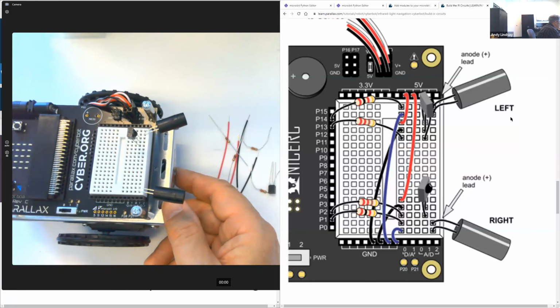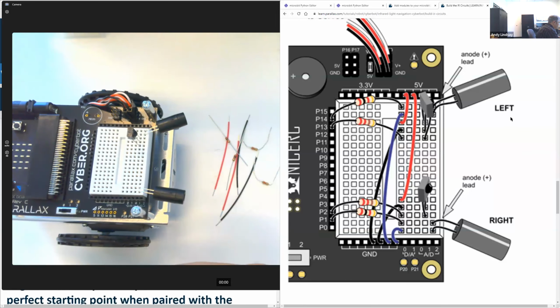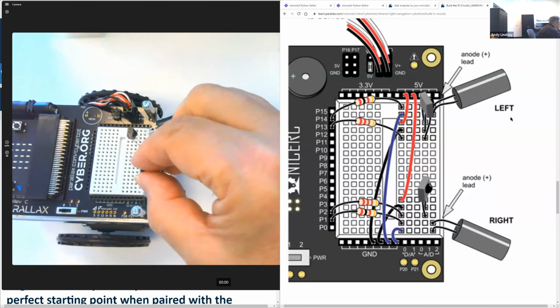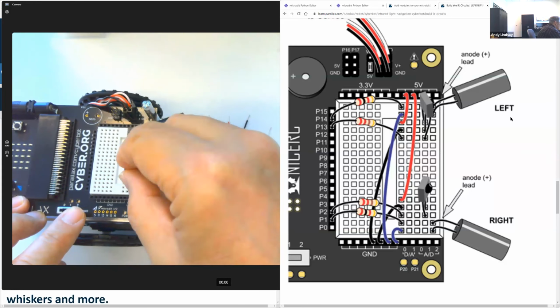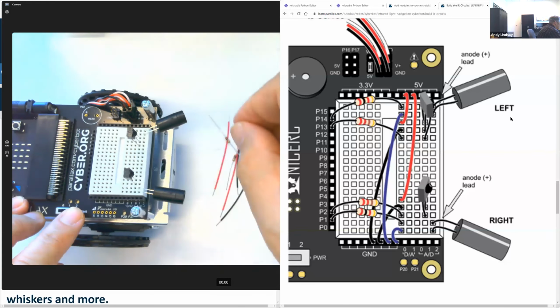When you apply voltage to the red bulbs, they have to be in a circuit with a resistor, and they will typically show about 1.6 volts. And then the resistor will show the rest of the voltage applied across the circuit. And then with an infrared LED, I think it's 2 or 2.1 volts or something like that.